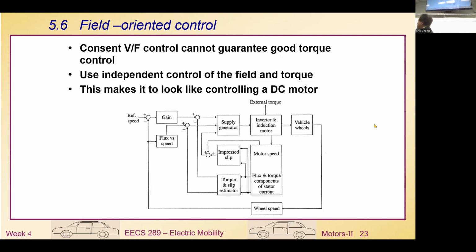This one is the so-called vector control we mentioned last week. When we control a motor, we are able to use the so-called field oriented control, FOC. With this method, we can separately control the torque and also the speed. So for the torque and speed here, we are able to control the amount of flux going into the motor system and also the torque per system. These two represent the torque current and the flux current. We are able to control that.